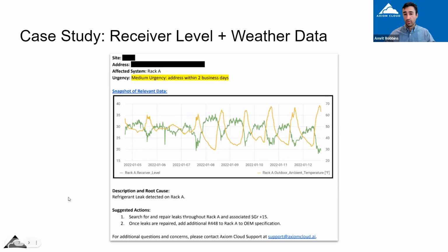And then we're able to normalize for all the other factors that cause big variations. Again, the really common ones being various types of heat reclaim, condenser split, outdoor air temperature, and a few others. When we're detecting a leak, we can't go to a technician and say, hey, look at this really cool digital twin AI-based analysis we've done. Instead, we have to put this into a form that's really digestible by a technician. And so that's what we've done here.